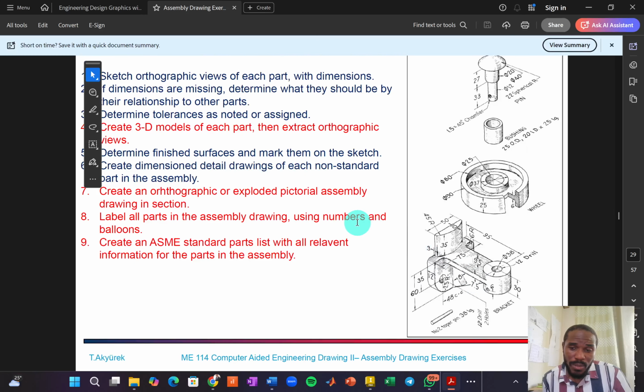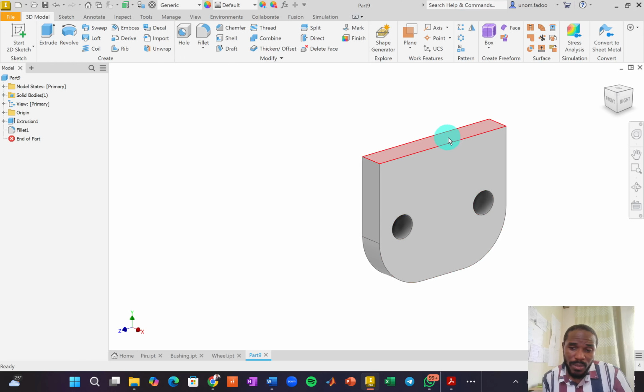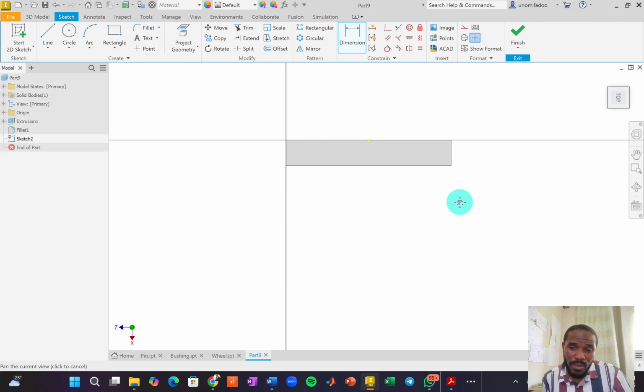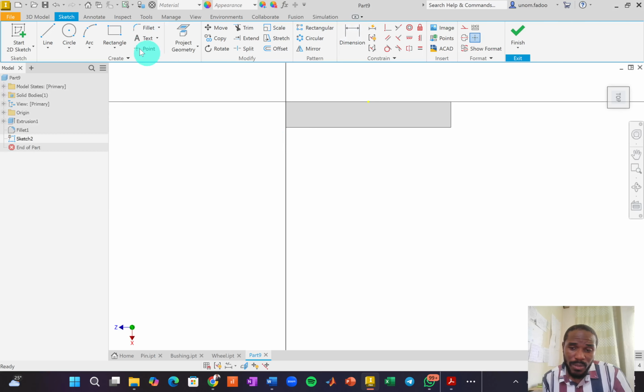So in my sketch, I want to sketch on that face, right? So I hover over the face until it's highlighted, left click, and select create sketch. Okay, so that's going to come up this way. This is where I'm creating the stuff I want to create. So I'm going to pick my 2-point rectangle tool, click and drag out.